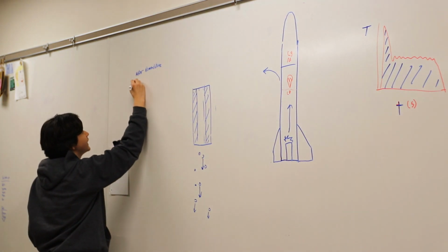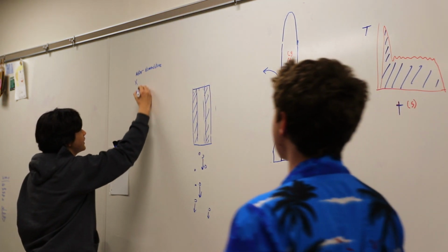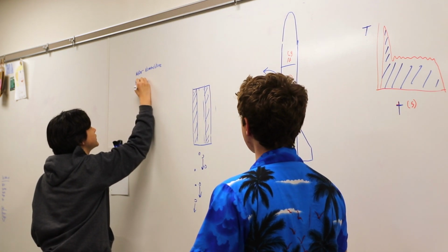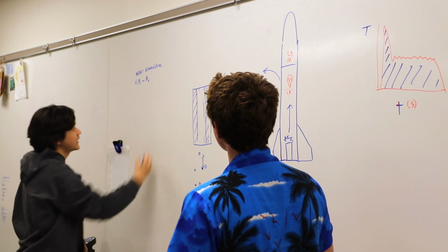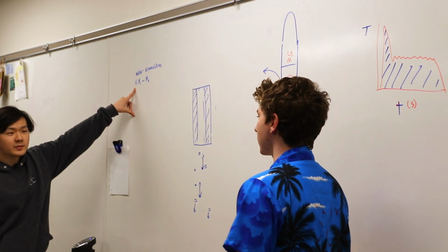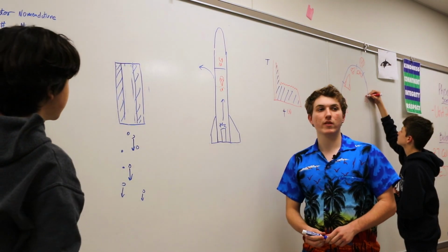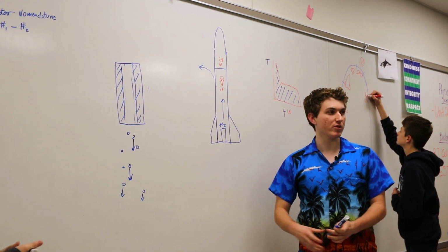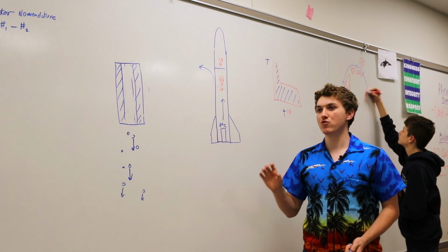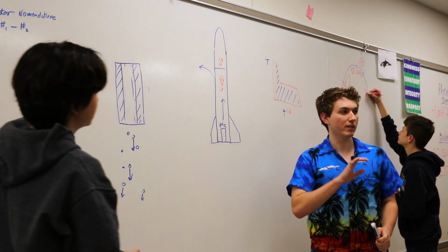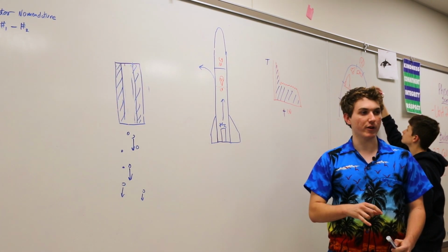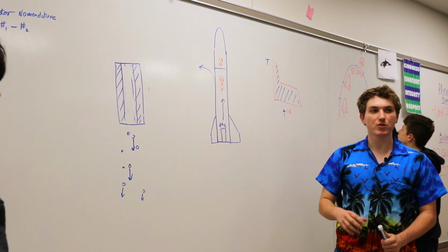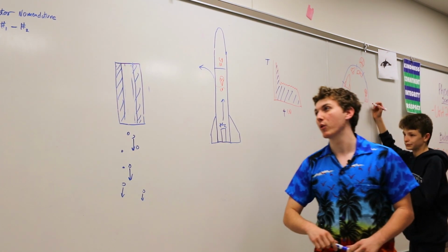You first have a letter, let's call it X, and then you have a number, 1, let's call it that, and then a dash, another number. I believe this is the impulse class. There are ways that you can classify motors. The first letter is how much general impulse there is. It'll be a letter starting from A all the way to O. We generally fly with Fs. Each letter is a doubling in total impulse, a doubling of total power coming from the motor.